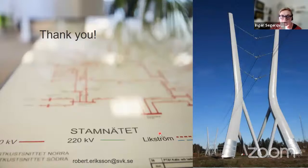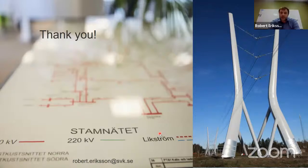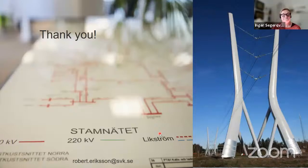And regarding this overload that you talked about, how long in seconds and how much per unit for the overload capability on HVDC links? It really depends on the technology. Some have almost zero overload capabilities, but others, like the older LCC, I think we have like 20-30% overload capability for half an hour or so. Okay.